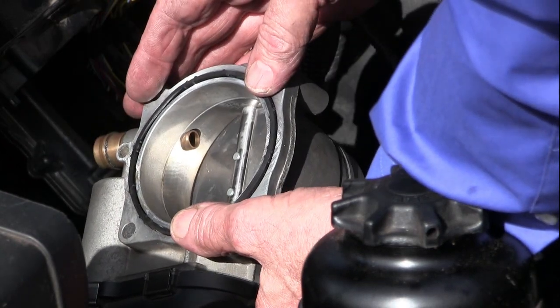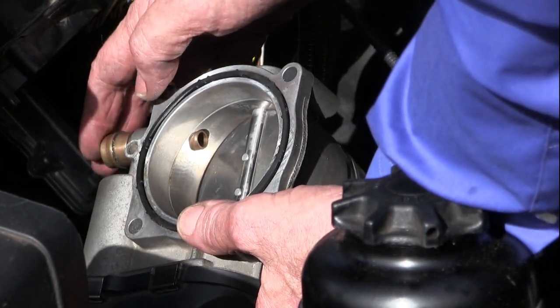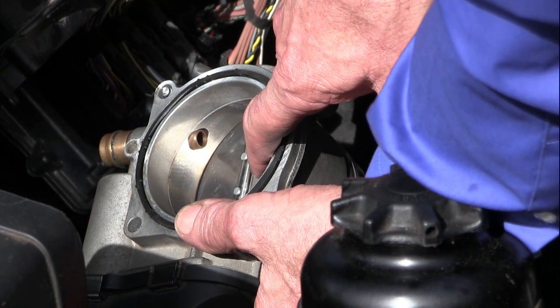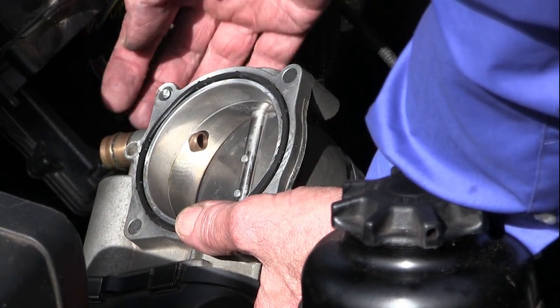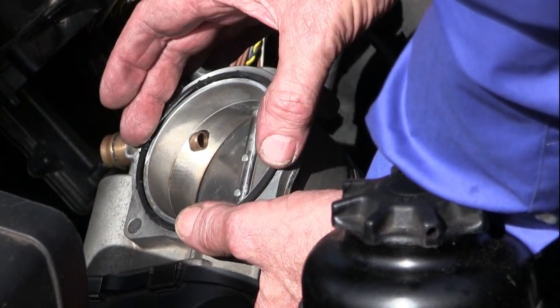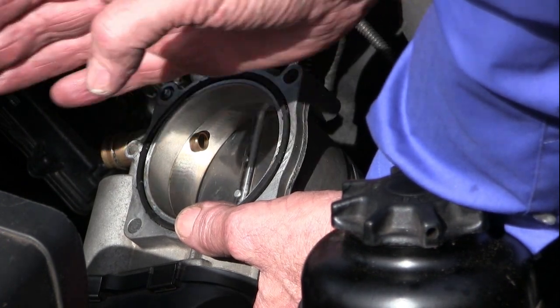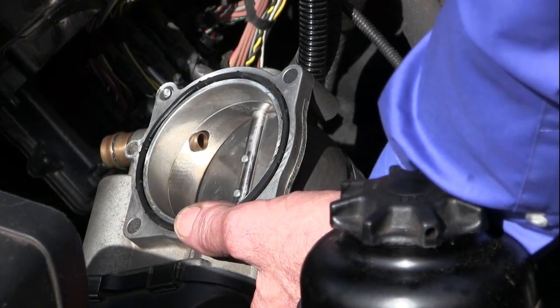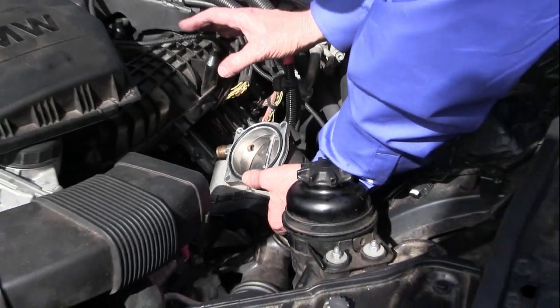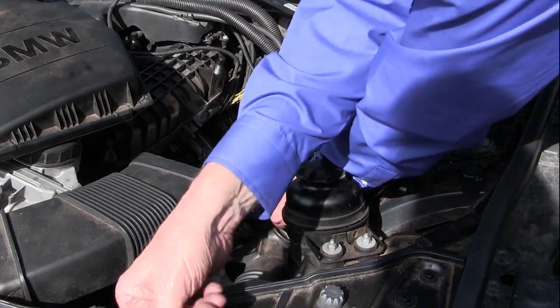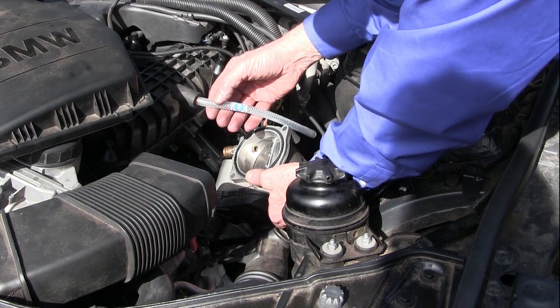Now that I've removed the throttle body back, we can see the port entrance, and the port entrance comes in behind the throttle blade. That will allow the 3C machine to fog chemical into the intake where it will be dispensed on the whole engine and evenly dispersed. Only use the ATS hose assembly.